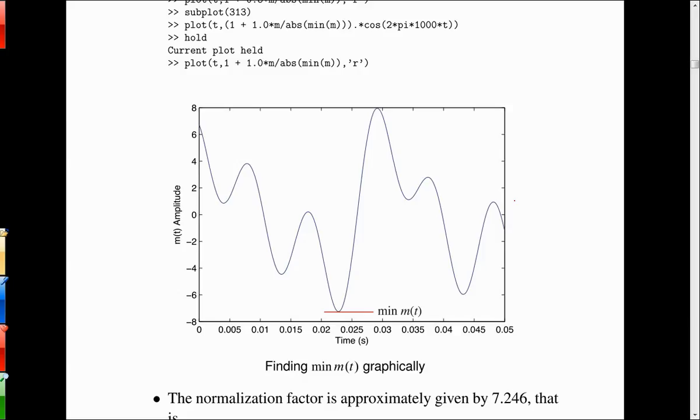I don't know, some of you listen to baseball or any sports on AM radio. Have you ever listened where the announcer is continuously jabbering away and you don't hear really any background noise or anything? But then as soon as he pauses or takes a breath, you hear this gasping sound because the gain of the amplifier rises up to try to renormalize everything to get the level as high as possible.